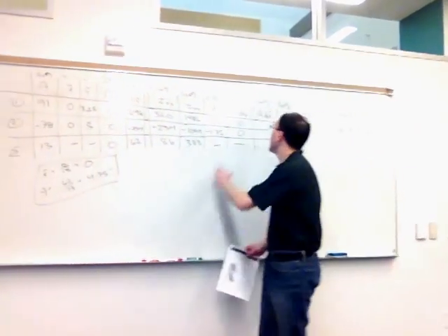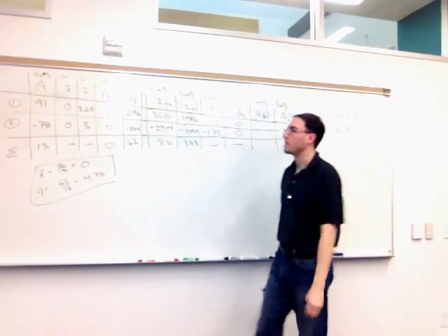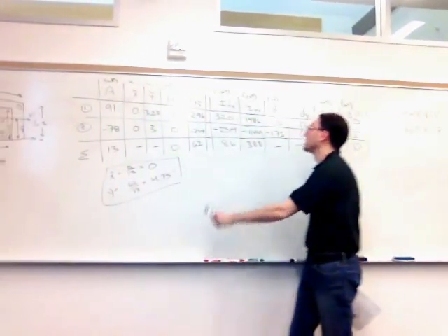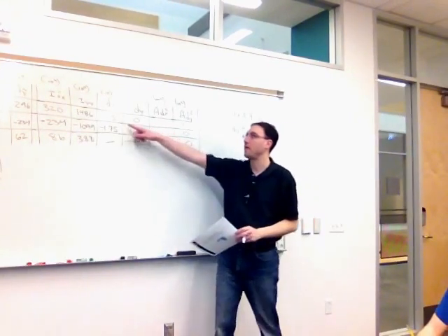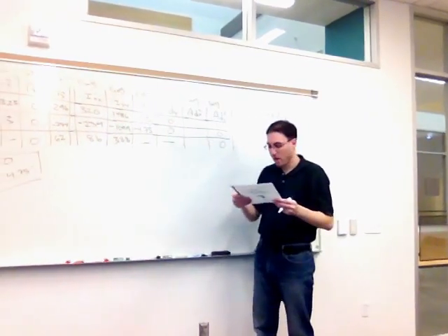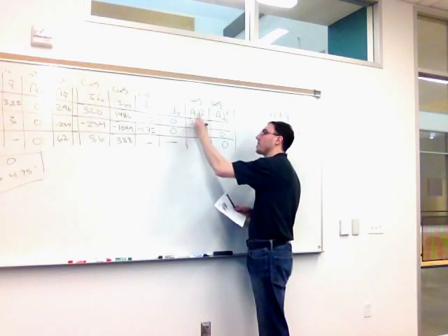And lastly, for Adx squared, I'm going to get 91 times quantity negative 1.5 squared. Gives me a positive value since that's being squared. I get 205 for shape number 1.